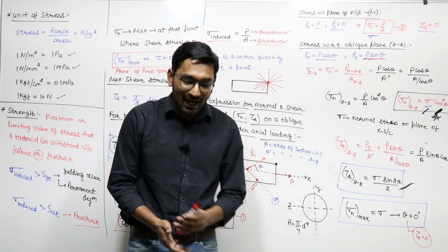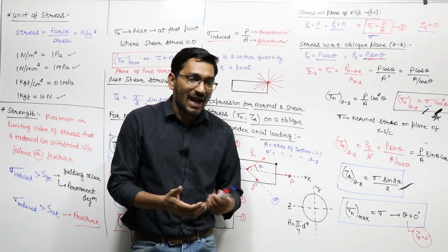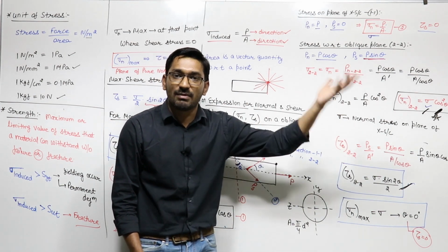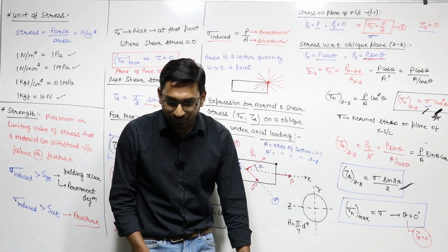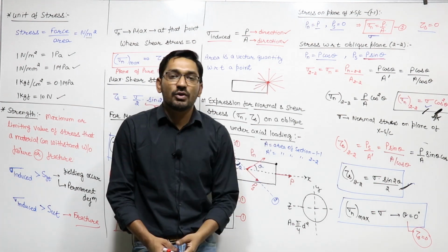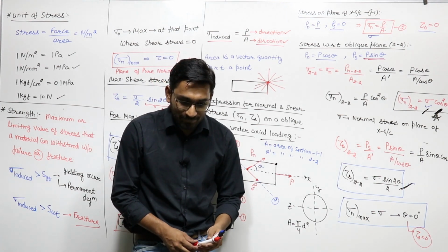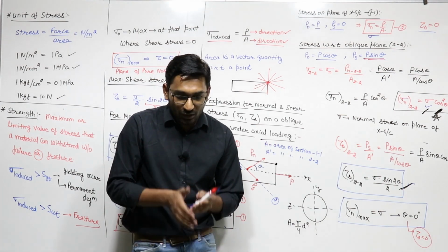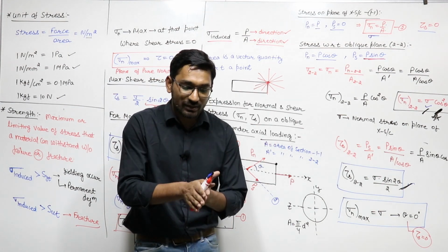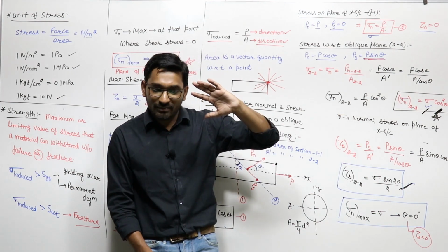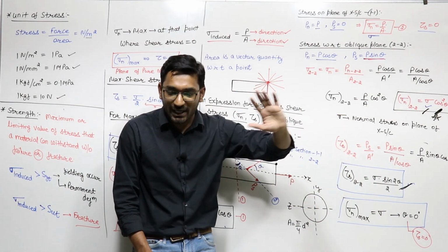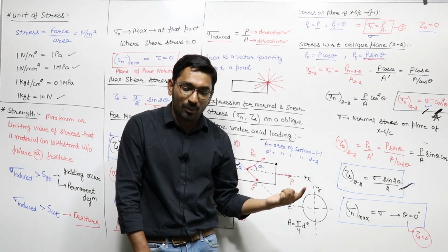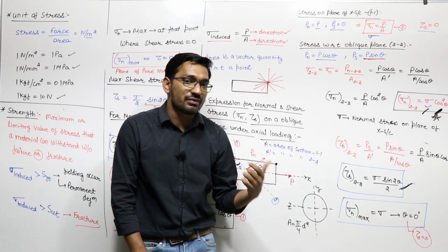So from this we have some conclusions for pure normal, pure shear, maximum normal, maximum shear stress. Some other conclusions also we can find out from these equations, we can find out normal stress and shear stress on any oblique plane, because theta is there, at any theta you can find normal stress and shear stress passing through a point under uniaxial state of stress.